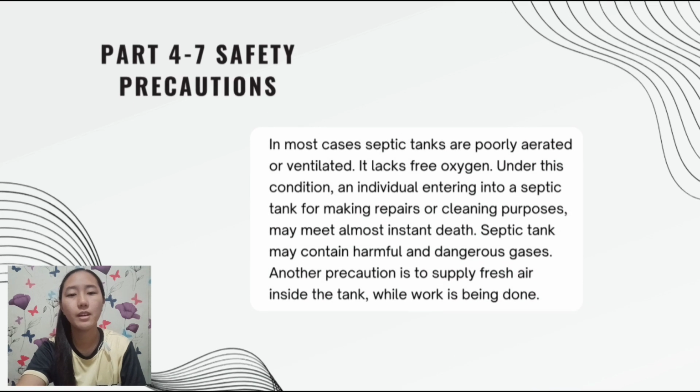Number 4 to 7 naman is safety precautions. In most cases, septic tanks are poorly aerated or ventilated. It lacks free oxygen. Under this condition, an individual entering into a septic tank for making repairs or cleaning purposes may meet almost instant death. Another precaution is to apply fresh air inside the tank while work is being done.